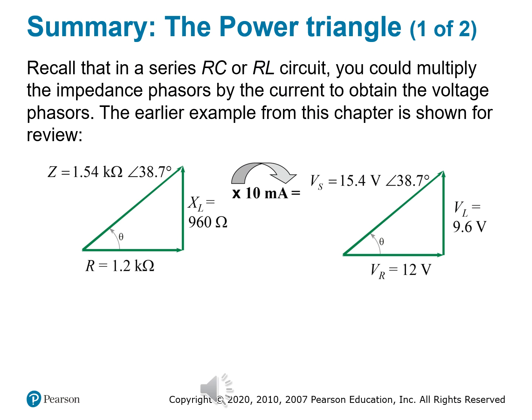All those voltages form the bases of the power triangle. They form a visual to help you understand how energy behaves in AC circuits. This is important because real power, denoted by capital P, is tied to V sub R, the resistive drop. Reactive power, denoted by Q, is tied to V sub L, that inductive drop. And then we have apparent power, denoted by S in this case, which is tied to the total supply voltage, V sub S.